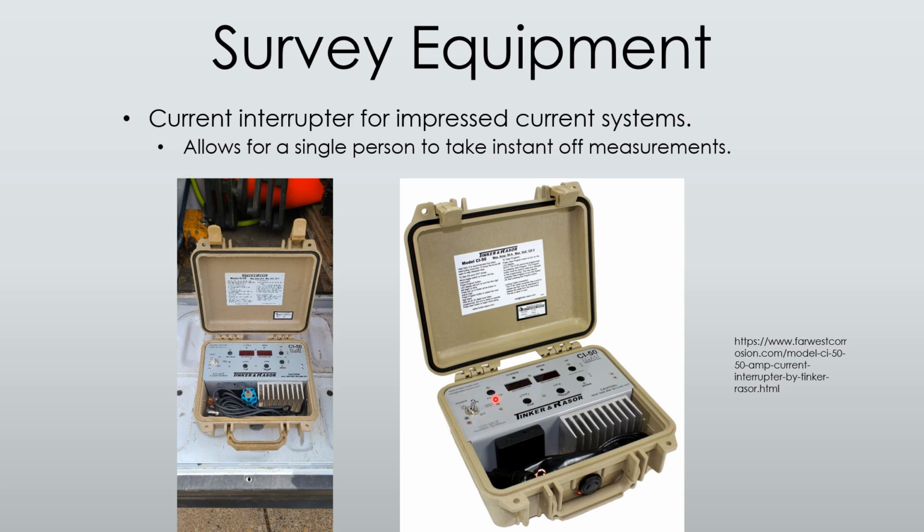You get your cycles. So for me, I do 10 seconds on, 1.5 seconds off. Some people do 5 to 1. You can do 3 to 1. I think you want to go at least a 4 to 1, 4 seconds on, 1 second off, at kind of a minimum, because you don't want the system to depolarize while you're taking your measurements as well.